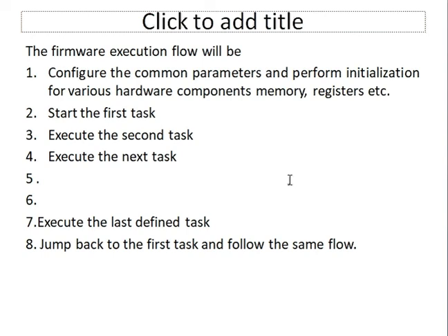Similarly, the communication speed, like the baud rate, we will address inside setup, and the task definitions you put always on a loop. So here void loop, its equivalent syntax in embedded C code is while of 1. While of 1 implies while true, always repeat the instructions inside the while loop, and it is equal to void loop in your Arduino programming language. So all the tasks need to be put inside loop, and the configuration part and initialization part has to be addressed in the setup loop.